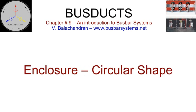Circular shape. Based on theoretical consideration, the circular shape of the enclosure is ideal for a three-phase, three-wire system. From the very nature of construction, it is evident that the field distribution will be uniform. Consequently, the bus duct will be most compact for a specified basic insulation level. The steady-state electrodynamic forces, on a three-phase fault, will be identical on all the three phases. The temperature distribution will be almost identical for all the three-phase conductors.